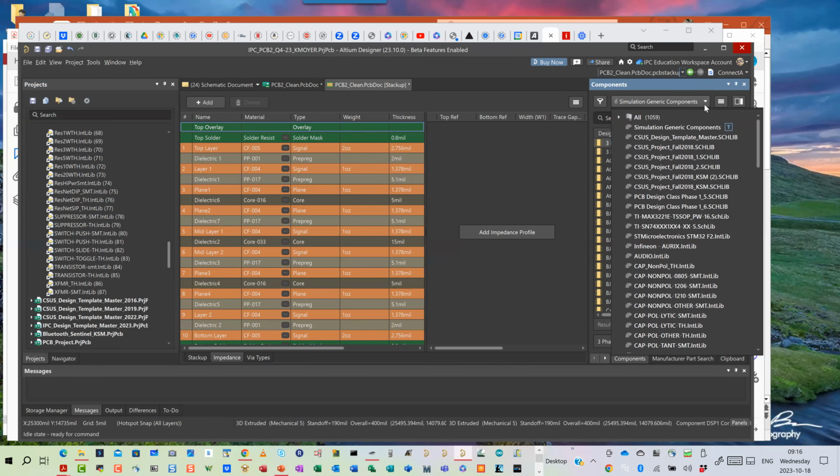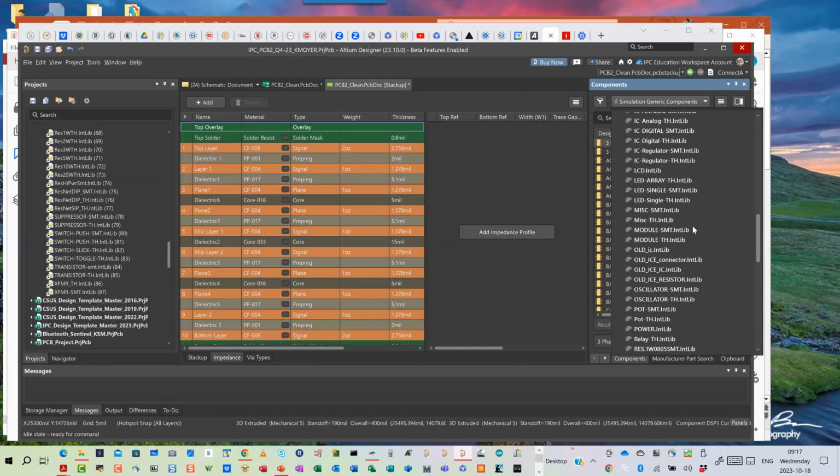So what I've done in the past at other companies, long before the days of Altium 365 and cloud, is I would have the IT people make me a folder on the server that had restricted access. The librarians had full editing and write capability to that folder, and all other users were read-only. I'd store all of my libraries in a network location on the folder, and then I'd create these IntLibs, and have the IntLibs attached here at the library level, right? So there's all those IntLibs.